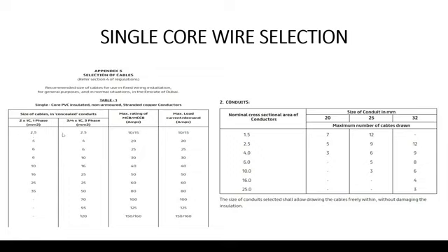How many wires do we use? As we explained in one of our earlier videos in detail on the load schedule, you use 3 wires for each circuit. You have the live, the neutral, and the earth. All of them are 2.5 mm. Then another example is a 20 amp breaker, which is a typical power circuit. You look through the table here and you would use 4 mm.